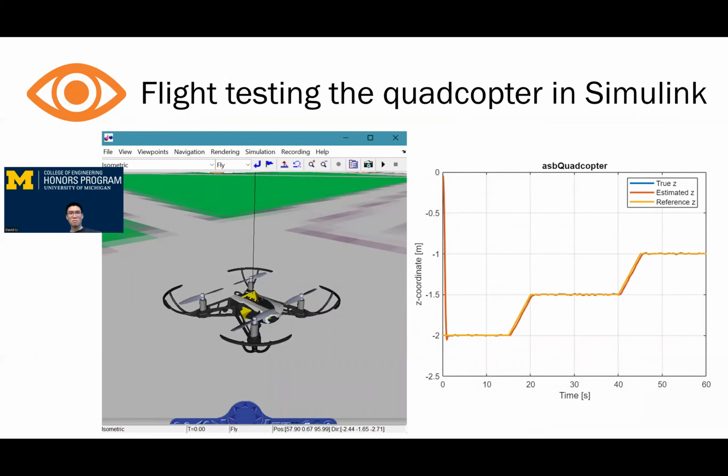So for most of this project, up until February this year, I worked exclusively in the Simulink environment. I came up with various testing scenarios for evaluating the quadcopter's performance with the current PID controllers. For example, for evaluating the altitude performance of the quadcopter, I started with what I call the constant altitude scenario, where the altitude reference is constant and non-zero throughout the simulation, but all the other references are constant and 0.